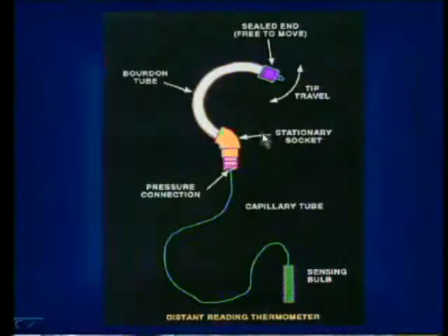In such a case, the measuring device will be at one place and the actual furnace at another, with some distance maintained. Even in thermal power plants, there is a control room, very distant, where we can find all the temperatures and how much power is generated. In such cases, these types of thermometers are used. Here this can be put inside, and we sense with the bulb. This is another type of thermocouple for distant reading.